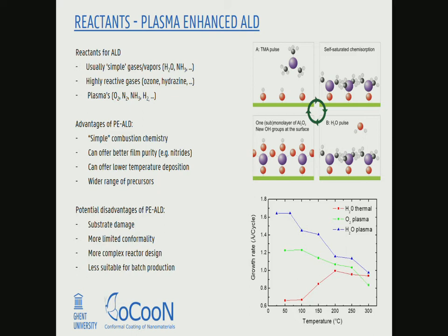Because you can so efficiently get rid of carbon, often it can result in better film purity. In the case of ALD, remember, you want to get rid of all of the carbon in your film, so the more reactive the agent that you're using here, the purer your film will be, and it can also offer deposition at lower temperature.